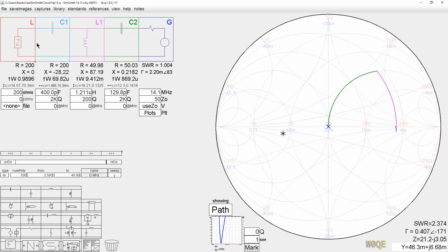This network matched a lot of those impedances very, very nicely, did it fairly efficiently, not as efficiently as an L network, but it did it fairly efficiently, and it was easier to produce. However, it had no harmonic suppression in it. It's a high-pass network. The harmonics of the transmitter go right through it. So there were some bright ideas that came around. And the first idea, I don't know who beats who in terms of time, but there were two variations on the T network that came about.